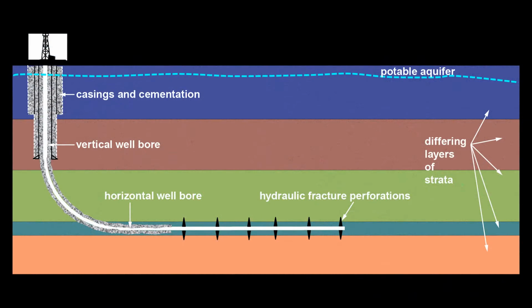Horizontal drilling is most applicable in formations with natural vertical fractures, thin layered reservoirs, old reservoirs that no longer have an adequate drive mechanism, producing reservoirs with extremely high dip angles, exploration and development of inaccessible locations, and areas where environmental concerns minimize the number of surface locations. The industry has developed the latest technology capable of logging the horizontal open hole leg, inflating and isolating stages in order to identify the oil-water contacts and select the optimum hole intervals for stimulation.